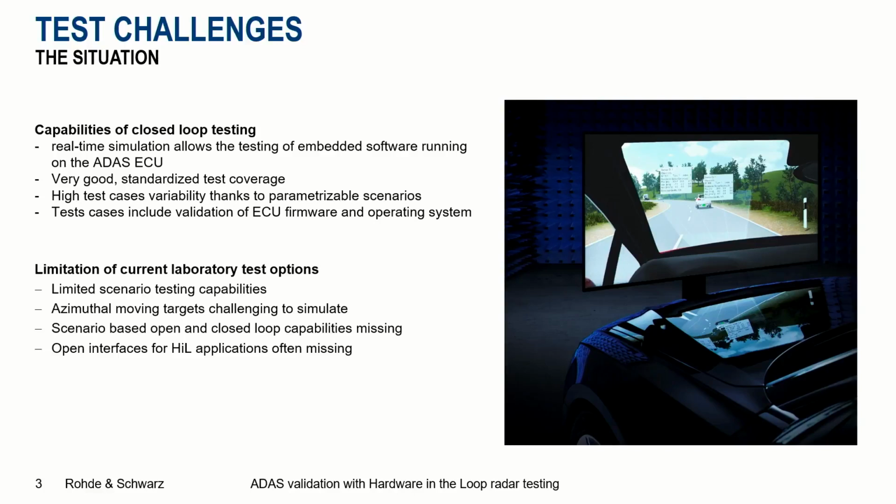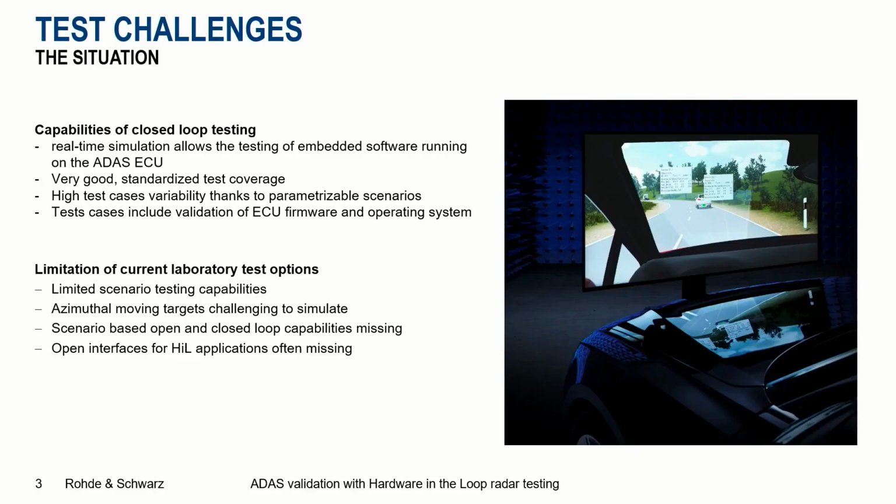And there is also a very high capability of parameterizing scenarios, so they can be automatically changed in some parameters, and therefore perform adjustments to certain predefined scenarios. And last but not least, as a further important factor, test cases include validation of the whole ECU firmware and even the whole operating system that is the foundation for the ADAS function.